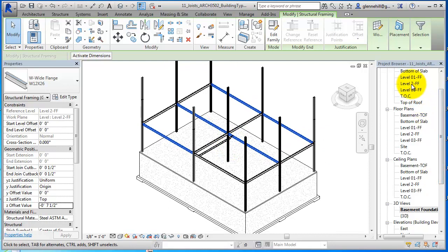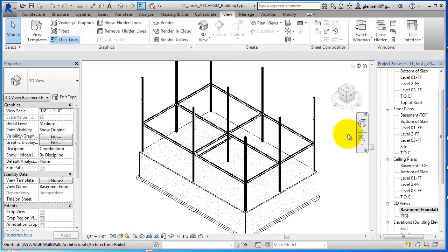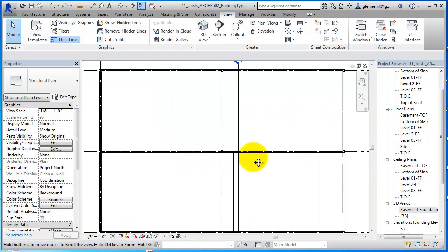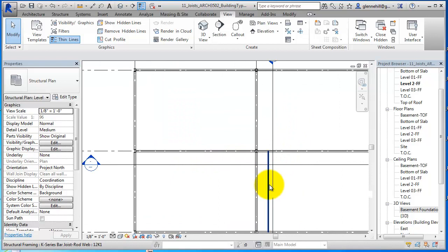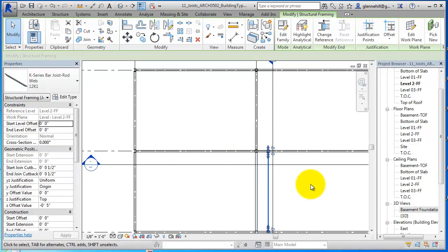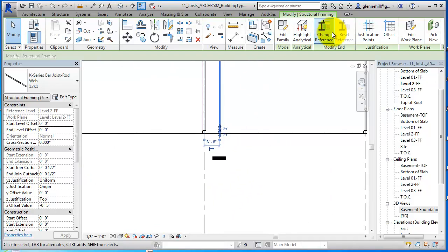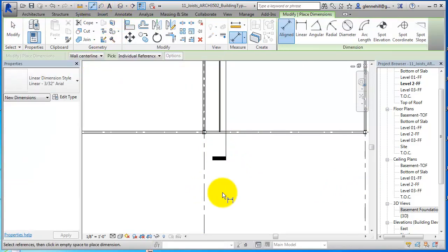So we're going to go back to our view. So I'm going to WT this and go back to our, we'll just go our plan view. There it is right there. And we're ready to put in beams. And so we could sit in here, measure them off, create them however we want. We want these at about 4 feet on center. And so I'm going to come in here and measure the distance here to kind of see how much. So I'm going to put a dimension in there so I'll have it for later usage.